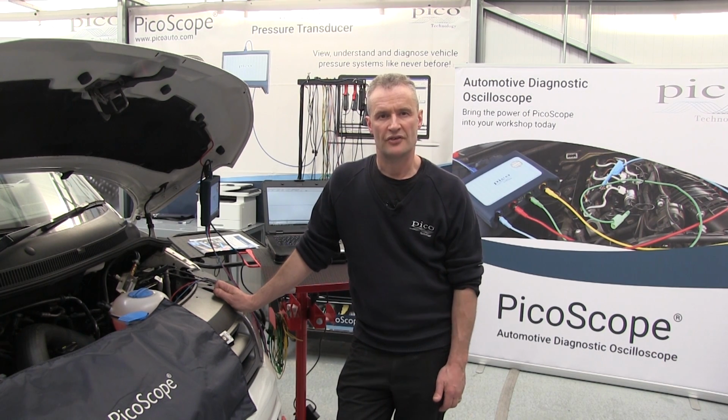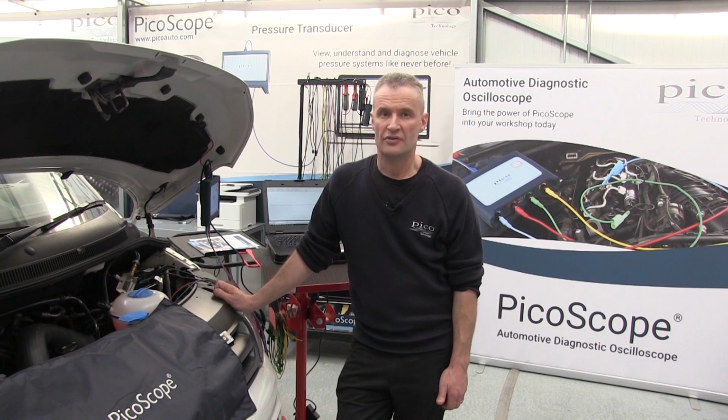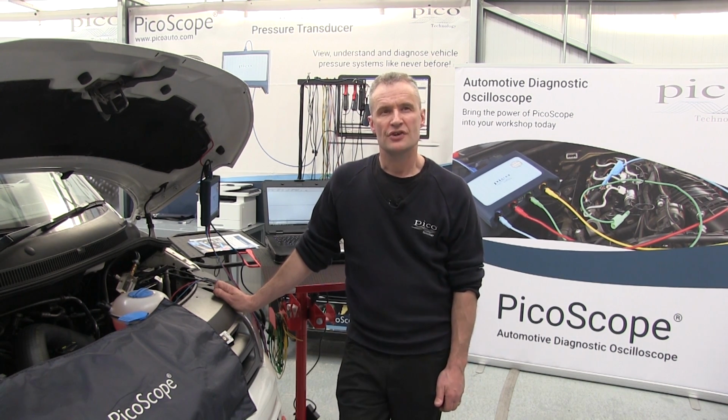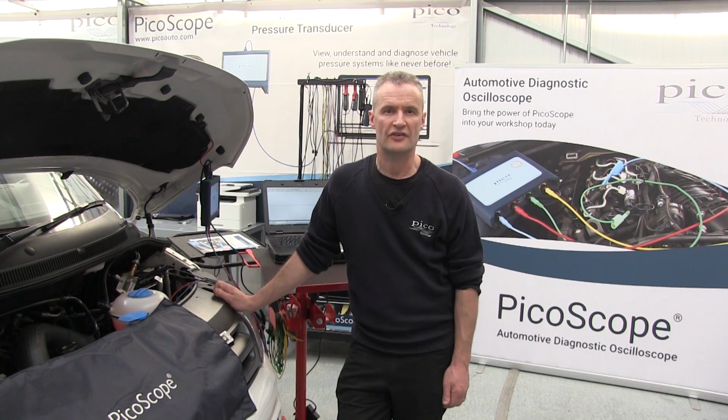We'll now set up PicoScope to look at the physical layer once again. We'll then apply maths to look at the differential voltage. We'll apply serial decoding and just look at how much detail is available in serial decoding. We'll use the export feature and the link file, and we'll also introduce not a fault, but we'll disconnect one of the ABS computers and export the data a second time and see if we can discover which IDs are missing from the network.